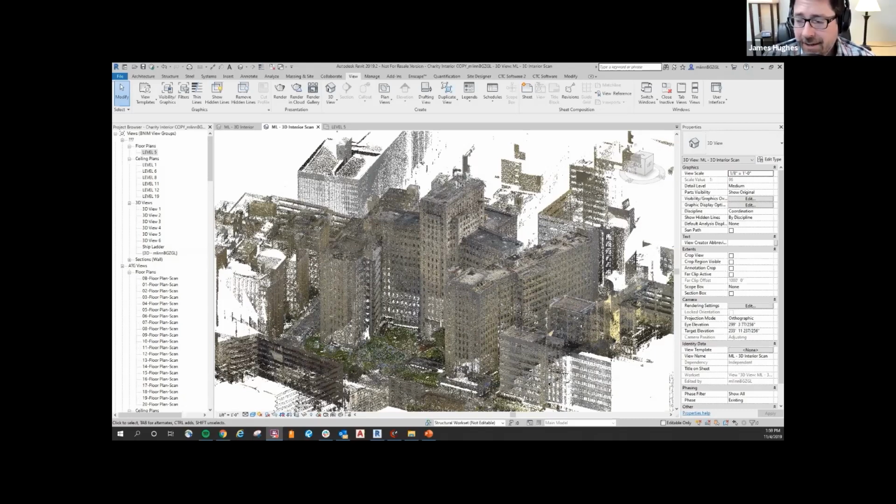It helps if you need to see. It's not an X-ray view, but if what you're looking at looks really flat, changing it over to that can help you actually detect when there is a verticality to the surface, or when there's lots of points on top of themselves. Normally, in a plan view, that means you're looking at something vertical. So if you're looking for columns or something like that, you could turn that on, and if they look like a square, just like everything else that's flat on the floor, it will then pop out a little bit more.